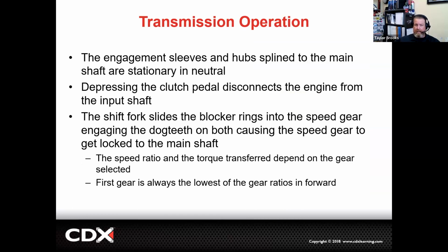Now, all of this, again, is going to rely on the driver to depress the clutch pedal to disconnect the engine from the input shaft of the transmission and allow for a smooth transition of the shift. Can you do clutchless shifts? Yes, you can. Is it a good idea? No. Usually it can do damage to the engine as well as the transmission itself. Unless you're super silky smooth, I do not recommend it.